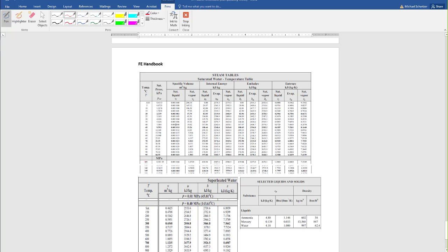So here, we're going to look at this row. We know the temperature here is 100 degrees if we're under the vapor dome, but the pressure, this constant pressure line, is 101.3 kilopascals. Now we have a specific volume of, what was it, 1.57 meters cubed per kilogram.